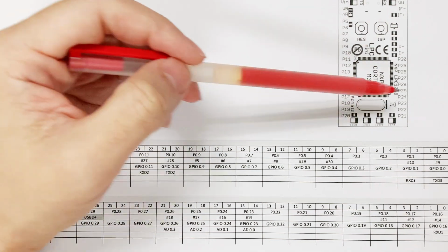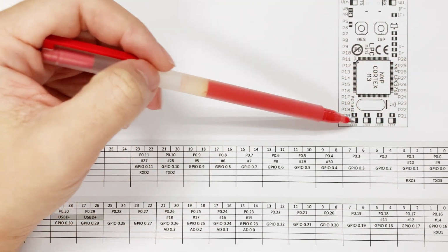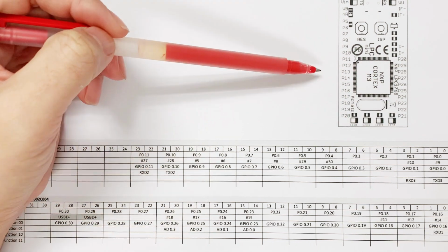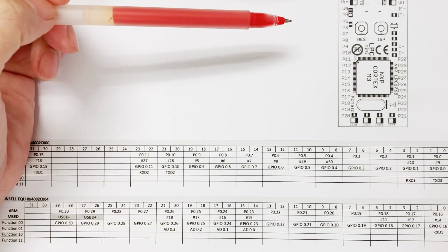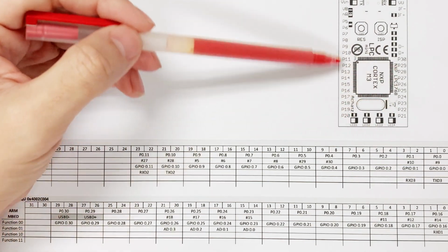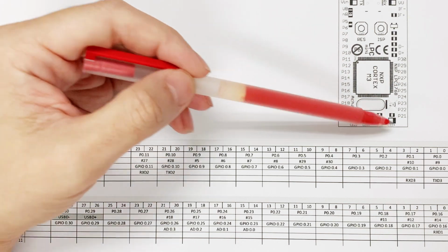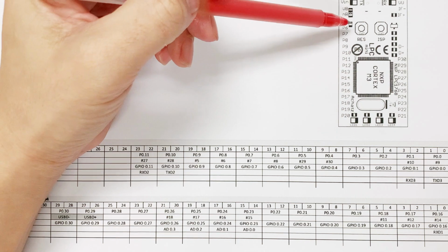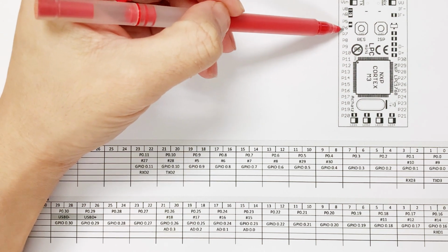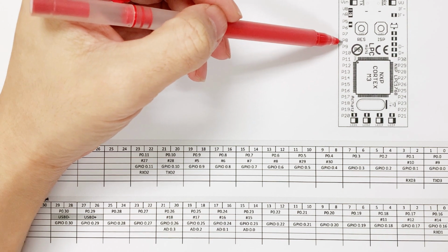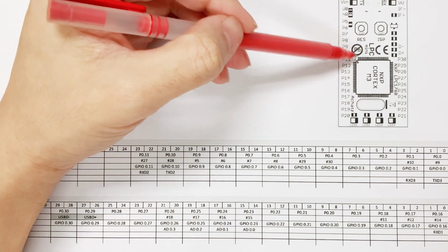The pin 5 up to pin 30 on the mbed module doesn't represent the ports that we discussed on the ARM GPIO. Therefore, before we can do any assembly program to interact with the GPIO of this mbed module, first we need to figure out for each of the pin outputs which port and which pin of the ARM microcontroller is actually connected.